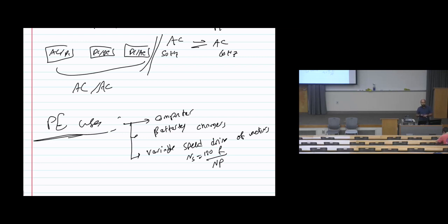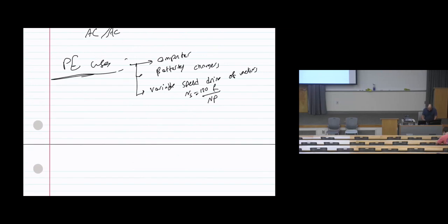you will see that most likely you will use, I'm not sure if you are familiar with Arduino or with motor controls, but in case you are, you will see in your code something called pulse width modulation or PWM. This PWM will go to the power electronics device, sometimes called a drive circuit. Then this will be used to control the motor. So you will see it everywhere: in your charger, in motor controls, in the computer, in battery chargers, and also in renewable energy.